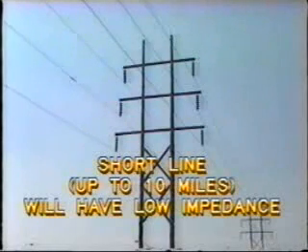This is used where the distance between each end of the line is quite short, say up to 10 miles. Indeed, at this short distance, other forms of protection, such as overcurrent or distance relays, are not very effective. Why is this? The problem with the distance relay is that the short transmission line will have quite low impedance, and therefore the relay will not be sufficiently accurate.